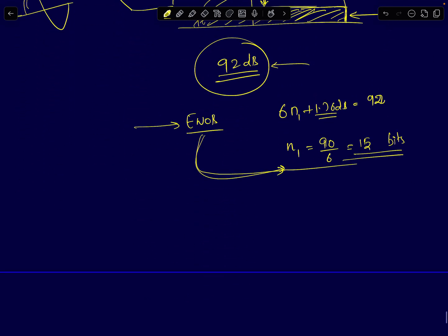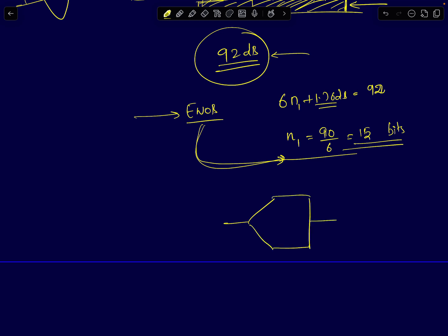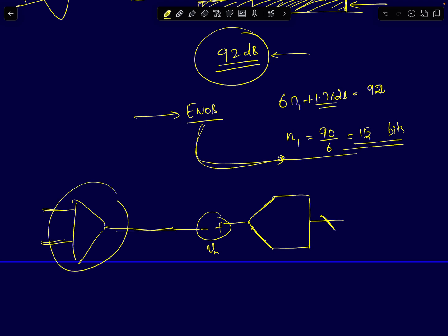So what is important is whenever you are having a high resolution ADC, these ADCs also will by default have very low thermal noise. We can model the ADC's noise at the input as an independent noise source, an input referred noise of the ADC. Now when you are amplifying the signal and feeding it to an ADC using an instrumentation amplifier, the noise added by the instrumentation amplifier should be much smaller than the noise added by the ADC itself. For high resolution ADCs which have high ENOB, in such cases, you need to have very low noise amplifiers. The amplifiers will definitely add noise. That should be much lower than the permissible noise due to the effective number of bits.